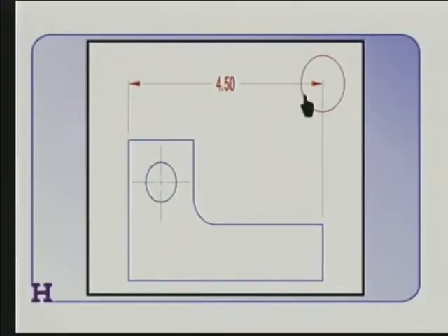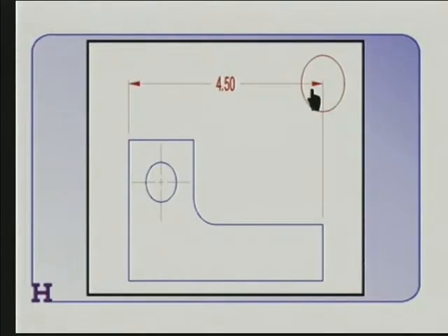It's a matter of personal preference sometimes whether you use filled arrowheads or open arrowheads. My personal preference happens to be filled arrowheads, and I'll tell you why. If you use the open style arrowheads, I have to back up and recall that no one ever looks at an original drawing. They only look at copies of the drawings. So what happens in the copying process when you use open arrowheads is they'll start to fill in, and each one will fill in slightly differently, and so the arrowheads will all look different.